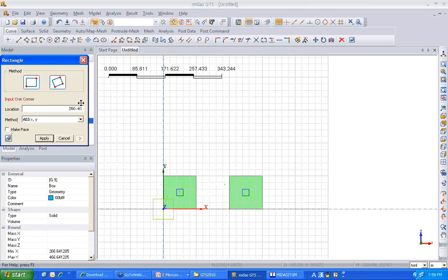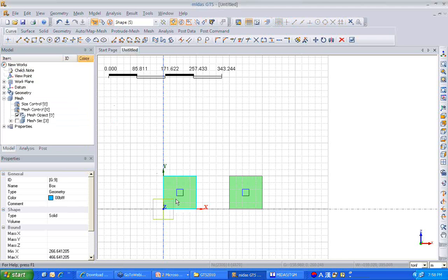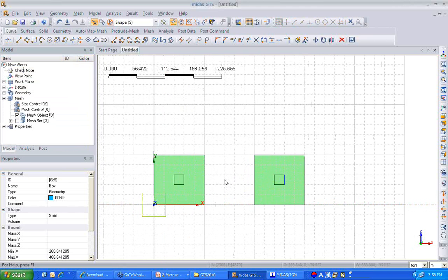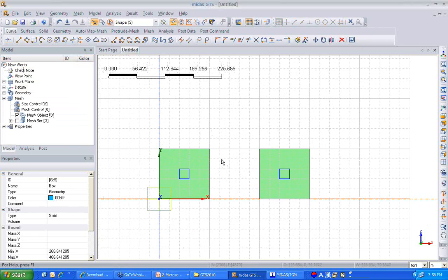So I will be auto meshing and map meshing a surface which has a cavity in it, and then I will show how different map mesher features allow you to have control on your meshing, and at the same time have a structured mesh, generating 8 nodal hexahedrons.